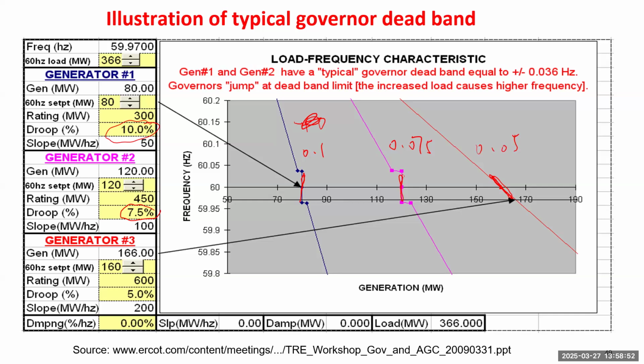Because in our early slide, we draw the generation in the Y and the frequency in the X. But anyway, so the third unit is the most sensitive, has smaller R, a bigger slope of control. Yeah, I also give you the value translated into the megawatt per hertz.